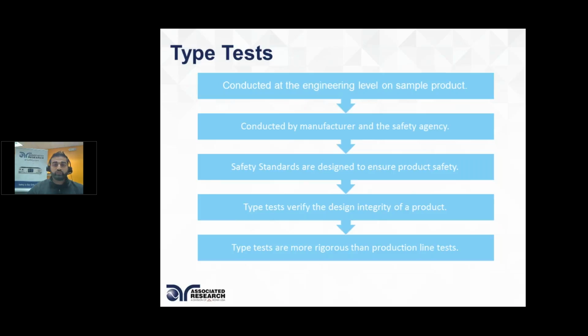Now, when you're designing the product, the standards will ask you to run a particular number of tests, and some of the tests call out for electrical safety testing. And in these tests is where you're making sure that the insulation protecting the end user from electrical shocks is there and is able to handle a particular amount of voltage that it might see in the life cycle of the product.